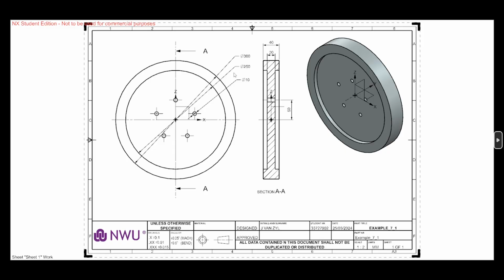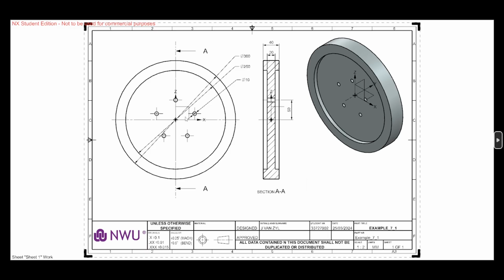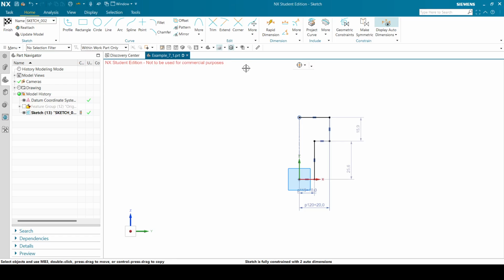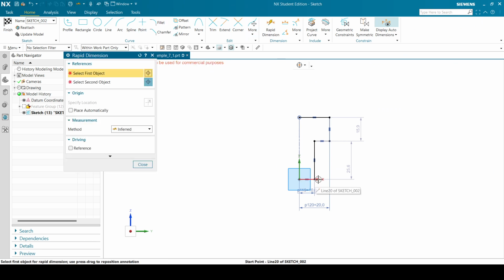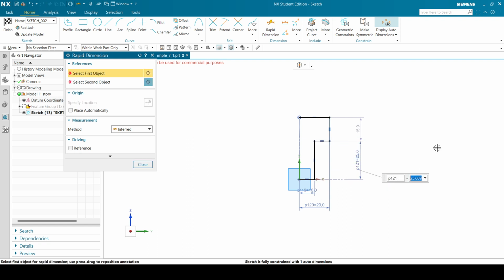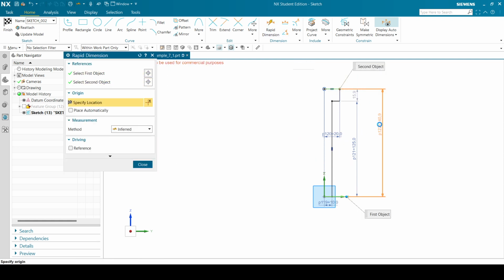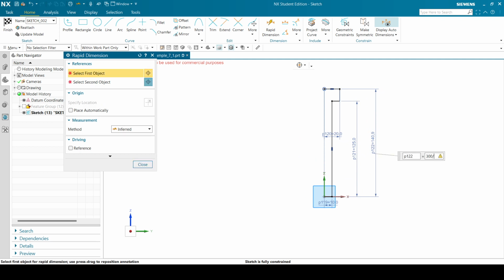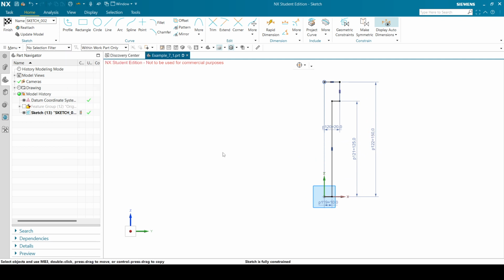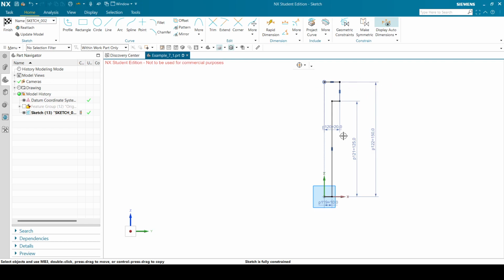Now we have our different diameters. I added diameter dimensions, but obviously you can just add linear dimensions here, as we're going to revolve it later. First, the inner one has a diameter of 250. So with rapid dimension from the horizontal axis to here, it's 250, but obviously 250 divided by 2. There we go. Close that. Then from here to the top, I believe it was 300. Let me quickly check that. Yes, 300 divided by 2. Okay, so that is the basic profile.